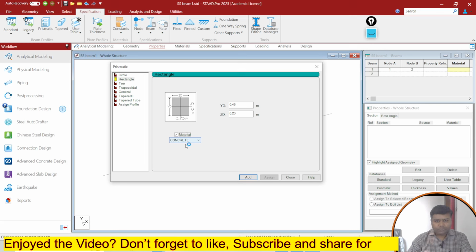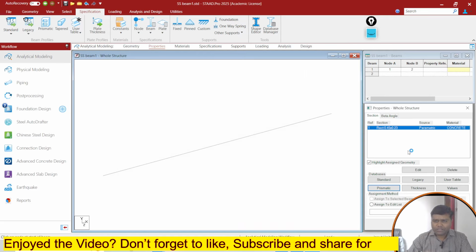Okay, we are using concrete material, so click on the concrete, or you can choose any material. But here we are interested in the concrete, so just click on the concrete, then click on the add. Then close it. Now see the properties we have added. Now I want to assign that property to the member. We have defined it now.